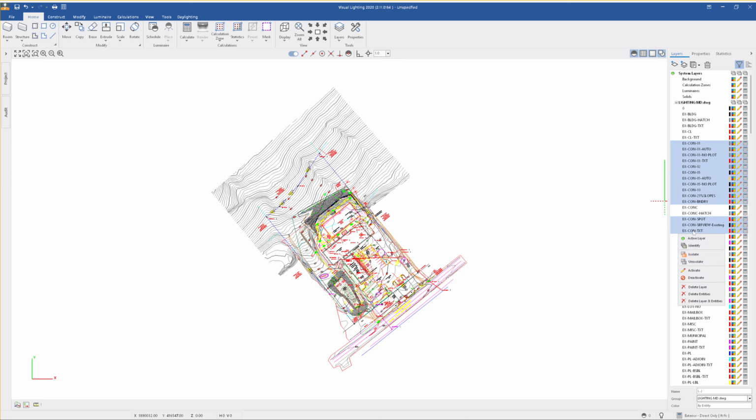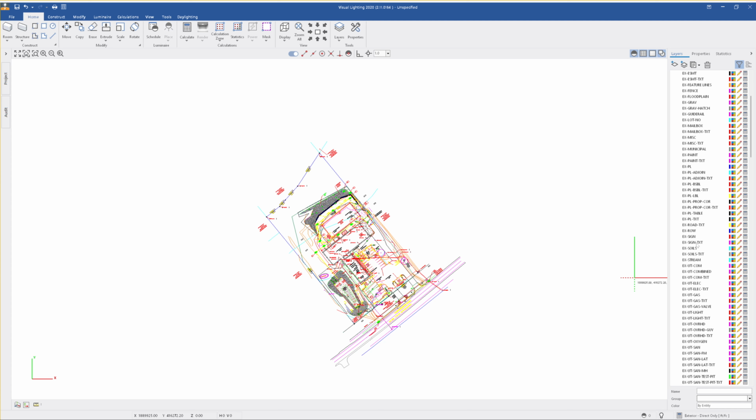So I can get rid of all the existing contours, those disappear. Any kind of existing soils I usually get rid of. Any ENS. So there's quite a few different layers that I try to get rid of to clean up the drawing, so it makes it easier for me to read what's going on.